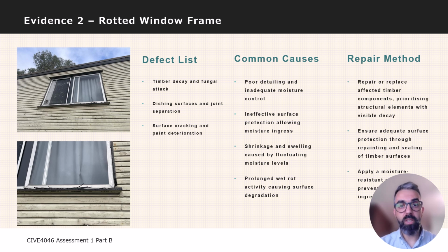Fungal treatments should be applied to alter the fungal activity and prevent further decay, including surface protection like repainting and sealing. It's a good moisture prevention, which stops water from ingress on the timbers and also inside of the property.